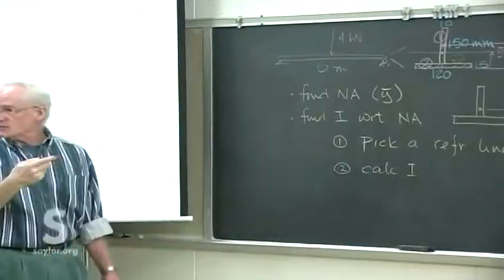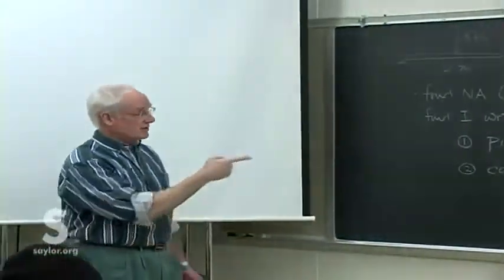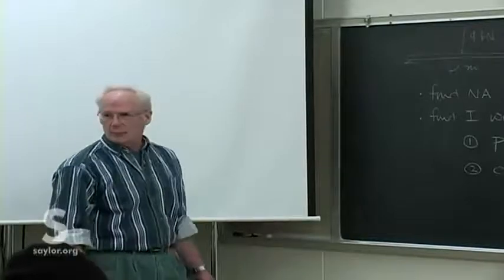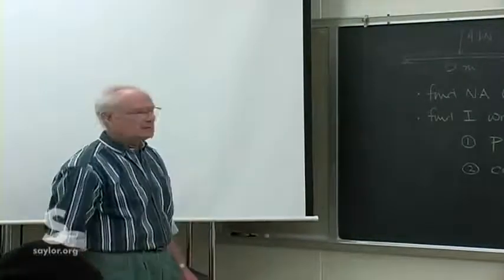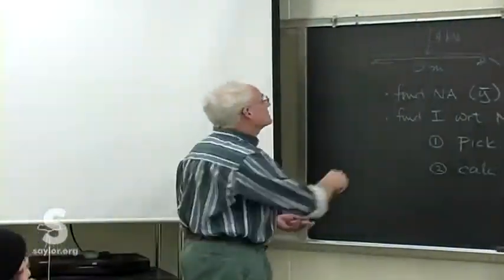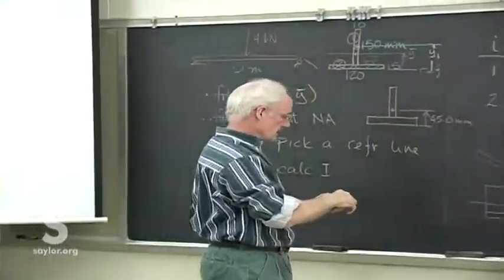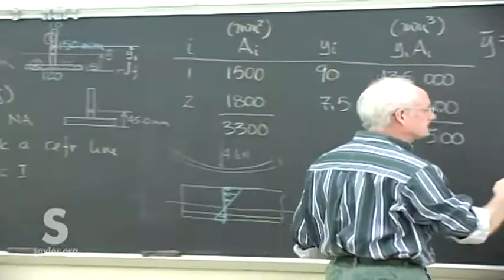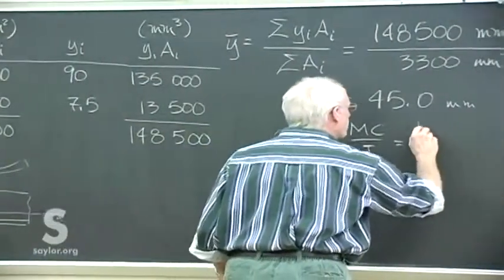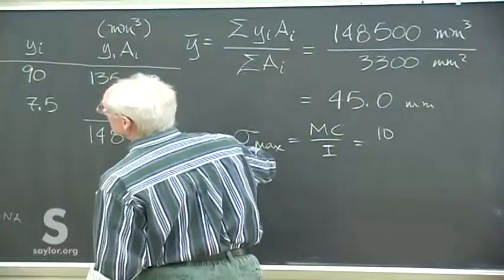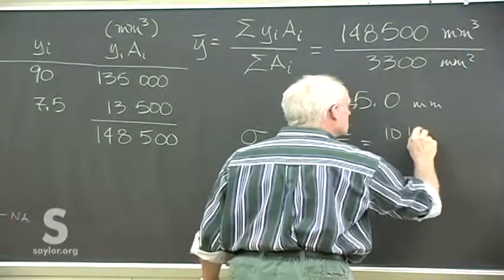It's going to have maximum moment right in the center. As you'd expect, if you were standing on a board like this, you'd expect it to break in the middle, right where you're standing. So it's 4 times 2.5, half the distance, which is 10 kilonewton meters.